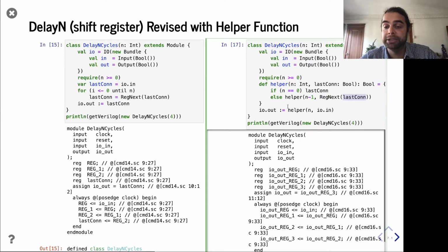And then we're also making connections in places like here, right? And so we perform all those connections. So yeah, we're instantiating registers and connecting them. And we happen to use recursion to organize this because, as we just saw, we can change this parameter and very fluidly change the depth of this shift register.